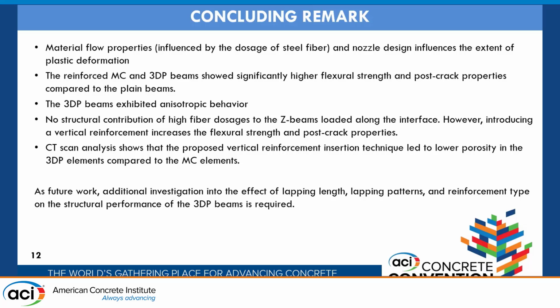And our result shows an anisotropic behavior, of course, which was due to loading in different directions. And in the case of the Z direction beam, we did not see any structural improvement even by using high dosages of fiber, but by introducing the short threaded reinforcement, we were able to significantly improve the flexural strength and also the post-crack properties as well. And finally, the CT scan analysis shows that our proposed vertical reinforcement insertion technique led to generally lower porosity in the 3D printed specimen as opposed to the modcast specimen.